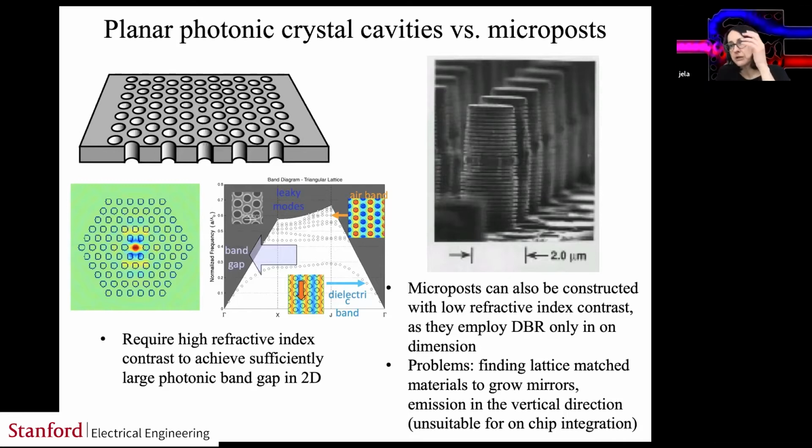So what they typically do is they make quantum wells based on phosphides, and then they wafer bond gallium arsenide and aluminum arsenide as mirrors because they're not absorbing there, but they can't really be grown directly on the phosphide materials. And if you just try to grow directly, there would be lattice mismatch and defects, and that would, of course, cause additional absorption and roughness and Q degradation. So there are unsolved problems there.